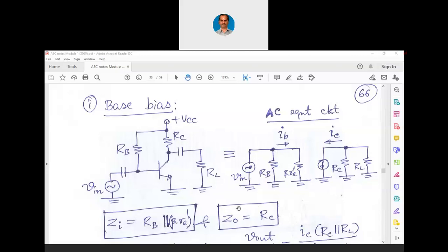Conversely, at the output we want to have a very low output impedance, because at the output we are connecting our load. So naturally our power supply should drive that load. Even AC current from the amplifier should go into the load. Think about this collector current AC. That AC current has to go into the load, which means there must be enough current at the output. If enough current has to be there, from the power supply only, all that current will be derived. So output impedance has to be ideally very low. I hope you got it now. Let me proceed with the discussion now.